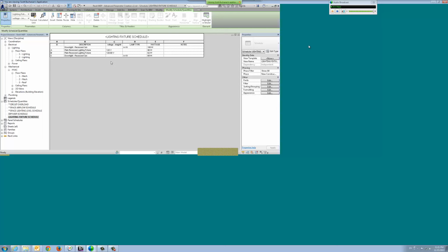It's also static at that point in time. So if you go through and you switch out lights, from 120s to 277s, you would need to rerun that tool. That way it will overwrite this existing data or fill out the new data that's potentially blank as well. So again, that's taking a look at a parameter, porting it across there, making it part of the schedule. That way I can start to use this thing and have a more realistic luminaire schedule.